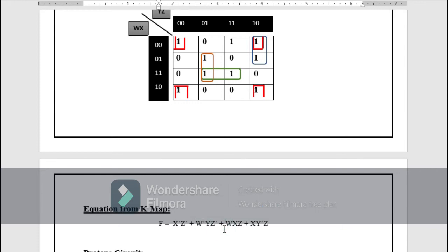Now I have completed all our theoretical part of the simplification of a circuit. I have made the truth table, then I have derived the Boolean expression from that truth table. After that I have made a K-map and then derived the simplified equation from the K-map. Now our next step is to make a circuit on Proteus from these truth table equation and K-map equation and simulate it, and to verify that both equations give the same result.